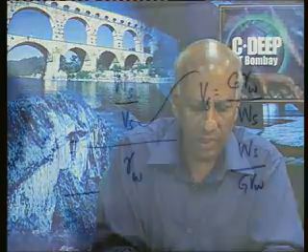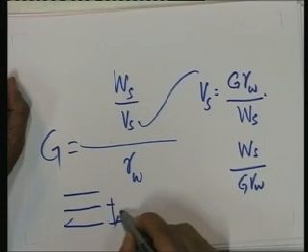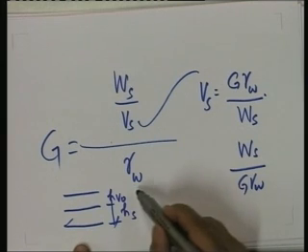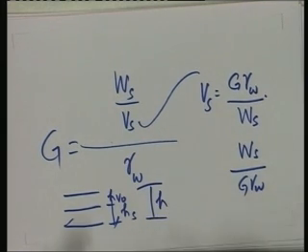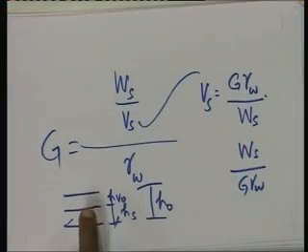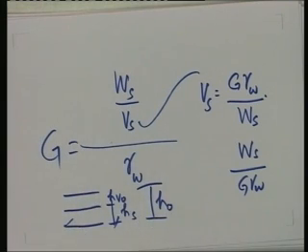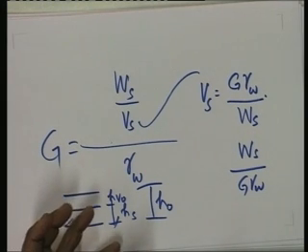So, at the starting point, if this is the height of solids and this is the initial height of voids, this can be obtained from the initial height of the sample h0 minus the height of solids, because the height of solids remains the same throughout the experiment, which means that at any instant of time during the experiment, the height of the voids, which will go on changing, will be equal to the previous height minus the change in height that takes place or change in dial gauge reading that takes place.